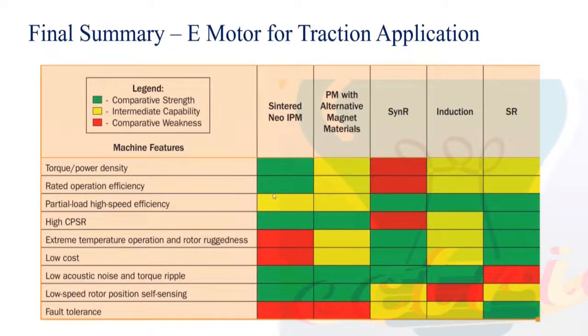When sizing a motor, we have to compare all these perspectives. Considering all of them, you see the PMSM motor has more advantages compared to the induction motor, and because of that it is ruling the passenger car market. And right now, as I told you, the synchronous reluctance motor has only a few disadvantages. Those disadvantages are being recovered by Tesla using permanent magnet assistance.